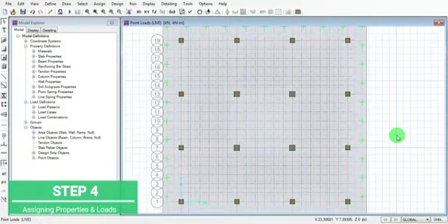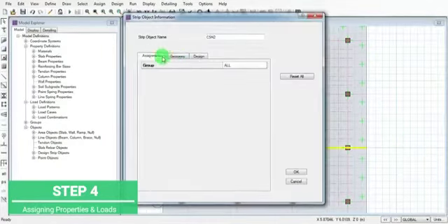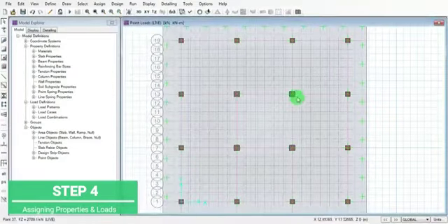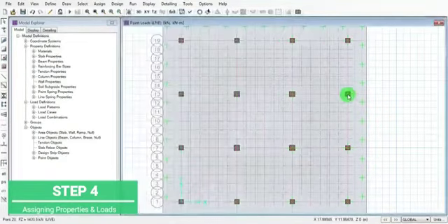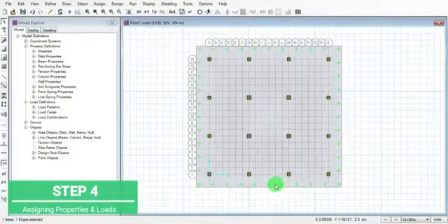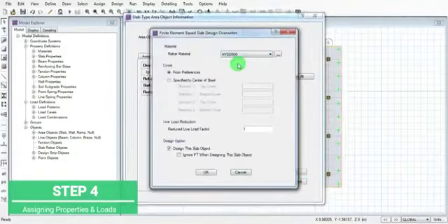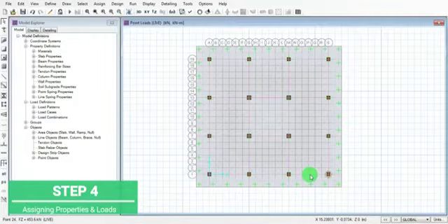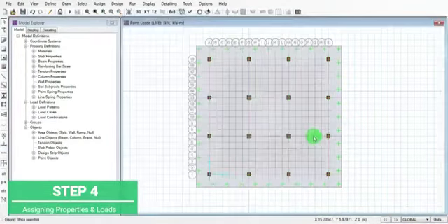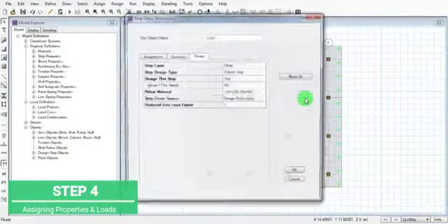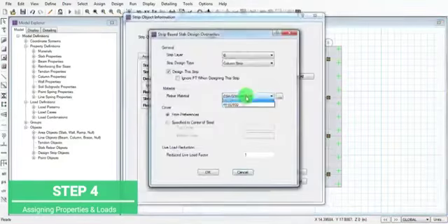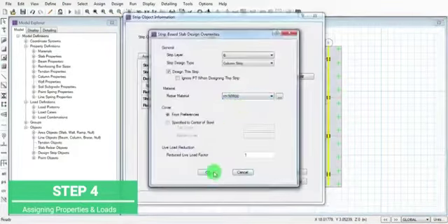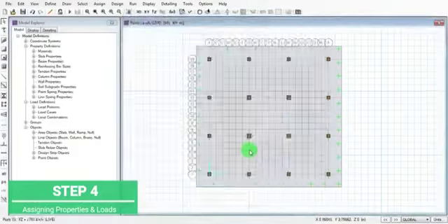Then we have to assign the rebar properties. Then click on okay, we are checking. Now select our footing, add the rebar options and add HYSD 500. Then click on the strips and add all the rebar properties. Click on all the strips of layer A and layer B.